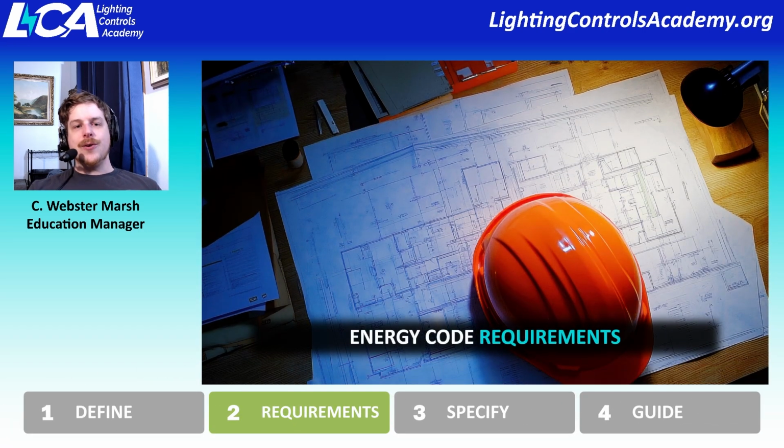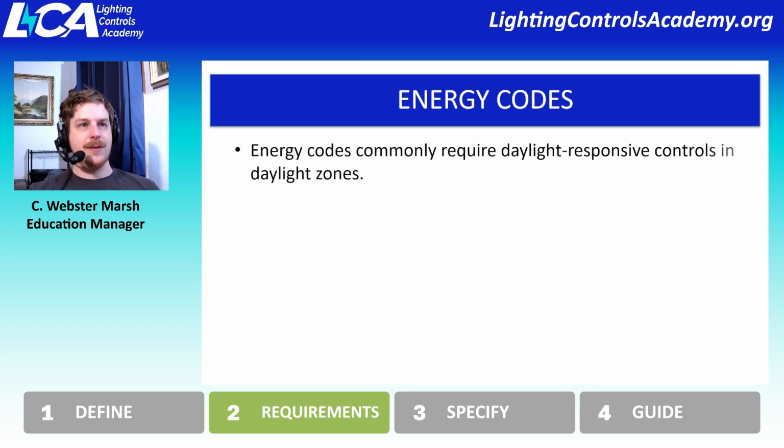All right. So energy code is the unfortunate reality of most commercial lighting controls projects. When you're working on a lighting controls system for a commercial building, you are going to be dealing with energy code requirements of one kind or another. So we're going to go a little bit into what kinds of expectations you need to adhere to when it comes to energy code. Energy codes, if you're unfamiliar with reading these, oftentimes do have some daylight responsive controls requirements, predominantly for how you zone your daylight responsive controls and your fixtures.